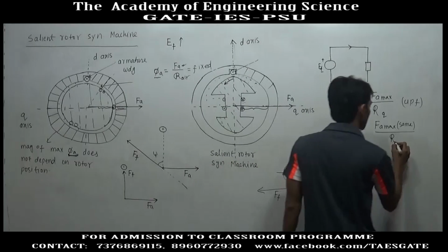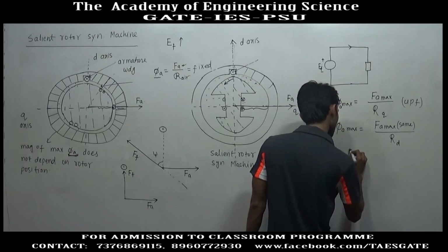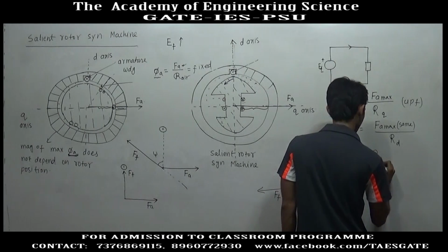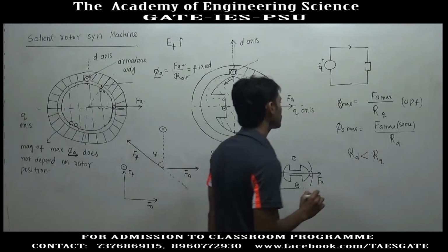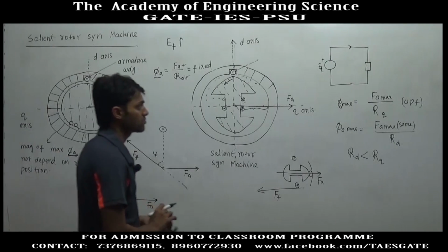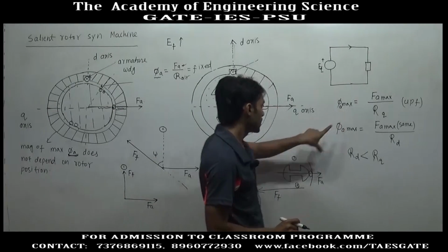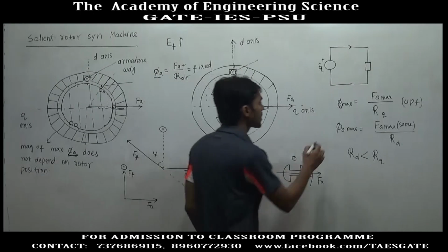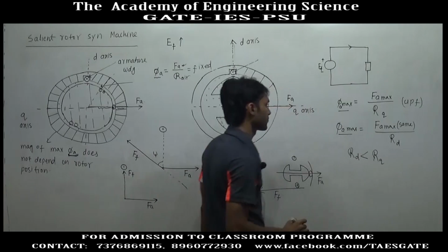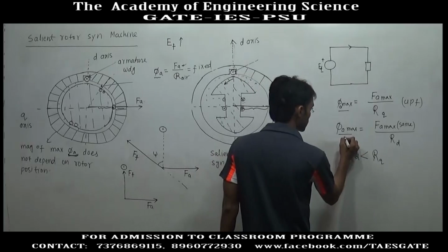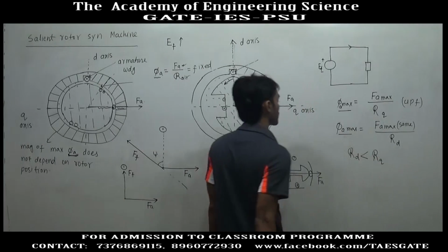So, this is the D axis reluctance, and the reluctance along the D axis is less than the reluctance along the Q axis. So, with the same maximum armature current or the same maximum armature MMF, if the power factor of the load is different, then the maximum armature flux is different. This is for a purely lagging load, and this is for a unity power factor load.